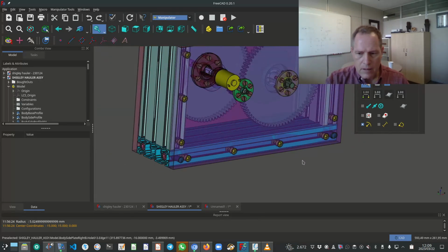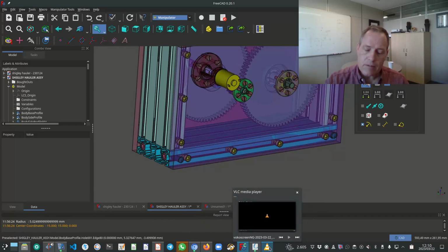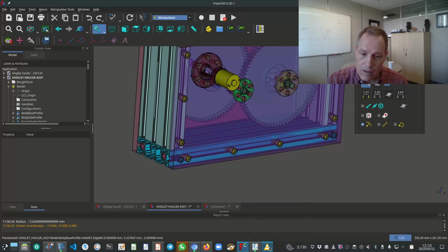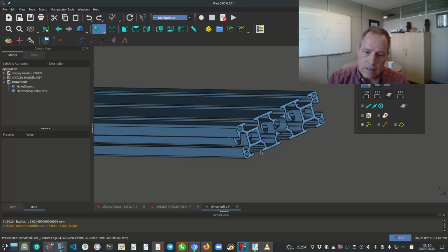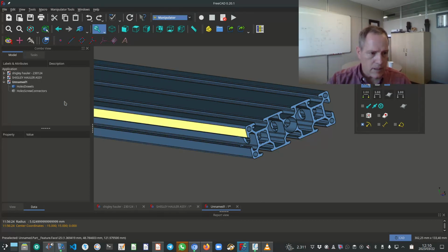The rest, I think, for the base plate, base profile stage 2 is actually straightforward. Just once again, any dimensions that are carried over from the stage 1 drawing, you can make reference dimensions. You don't have to. Any dimensions carried over from stage 1, tolerance them again. Only the features that are unique to stage 2 are the features that we will dimension. Alright, so that's the base profile stage 2.